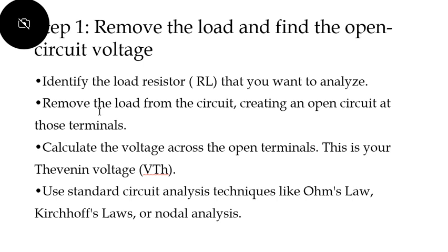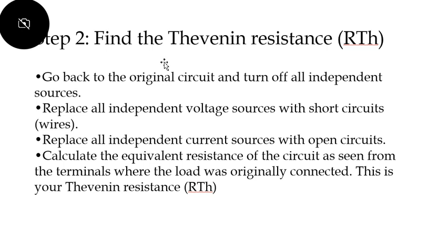You have to remove the load from the circuit, creating an open circuit at those terminals, and calculate the voltage across the open terminals. That voltage is your Thevenin's voltage. We use standard circuit analysis like Ohm's law, Kirchhoff's law, and nodal analysis to find the Thevenin's voltage. The next step is to find the Thevenin's resistance.